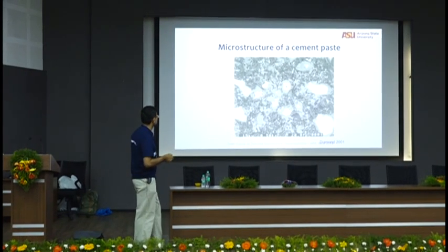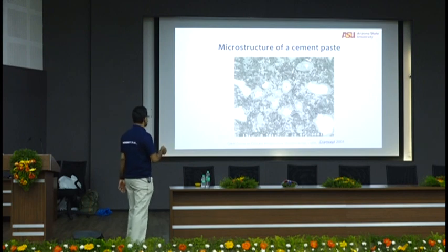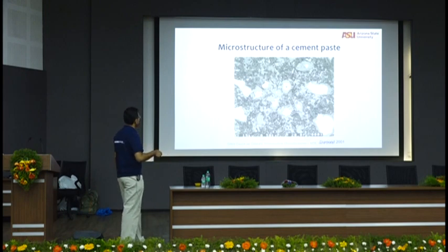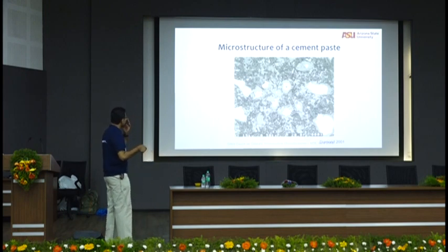Okay, maybe that's different. Okay, so here is a microstructure of a cement paste that you've seen. What is A? What is it likely to be? This is the hydrated cement, so could be the CSH around unhydrated cement. What is B? Where is B? I think this is B. What is B? A void. What is C? Unhydrated cement. What is D? All are hydration products, right? So again, you're comfortable with this idea.